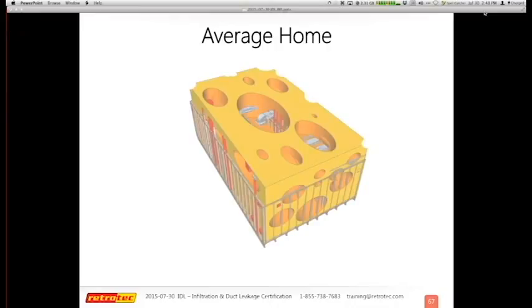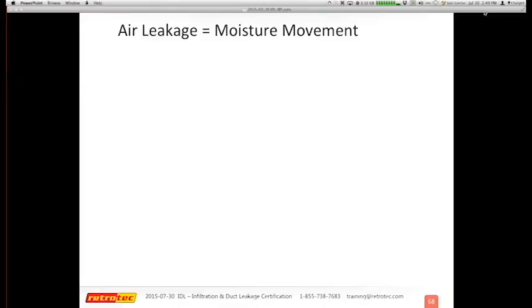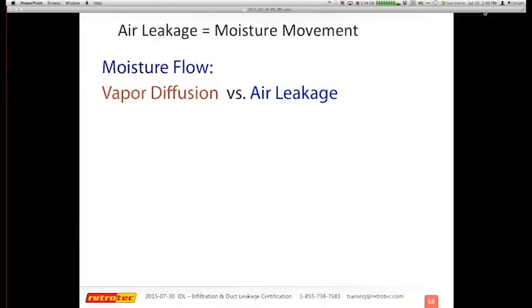So there actually are an enormous amount of connections that go through top plates and other connections to the attic or crawl space, and large ductwork moving through floors. All those things create an enormous amount of energy and air moving throughout the interior of the structure, let alone the outside of the structure. So there are multiple reasons to be controlling our air movement and flow.